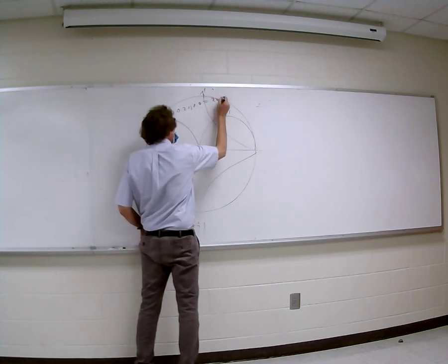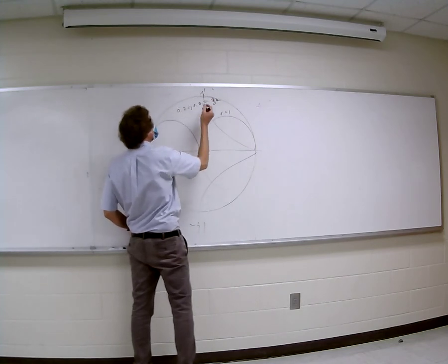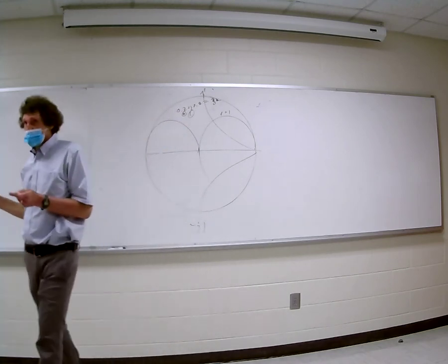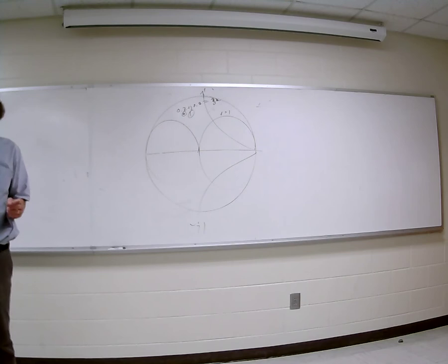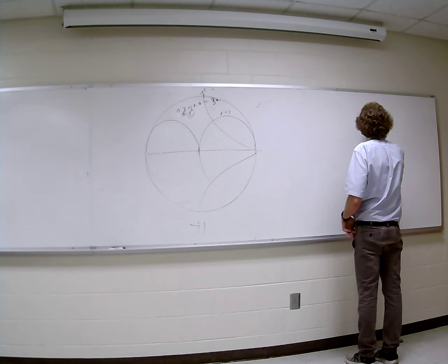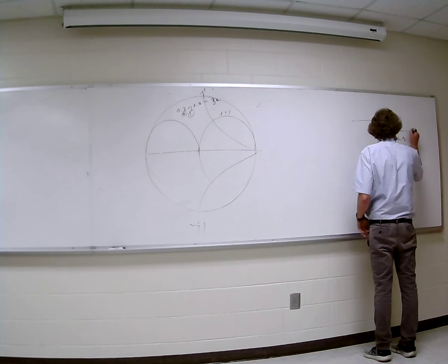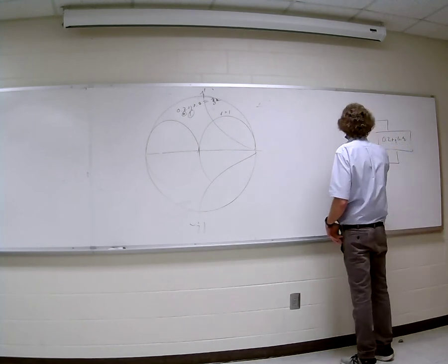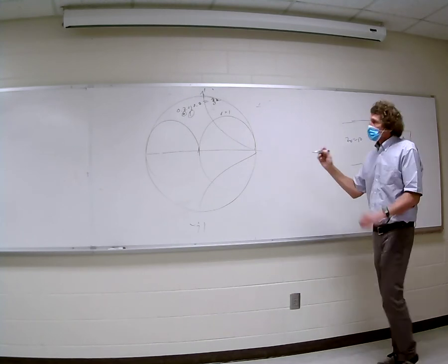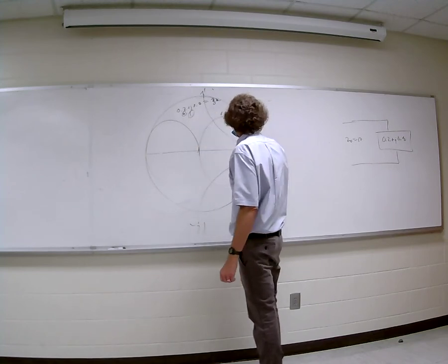We're going to label that Z normalized of the load. Yeah, it's right there. That's in the impedance domain, right? Now listen carefully. If we had impedance, it would be a series element. So here's our load. I don't care what the load is, but the normalized load is 0.2 plus J 0.8. Now just think about this. Let Z naught be equal to 50 ohms. I want an L section matching network. Now, you know the trajectory does this, right? You all see what I'm doing here?